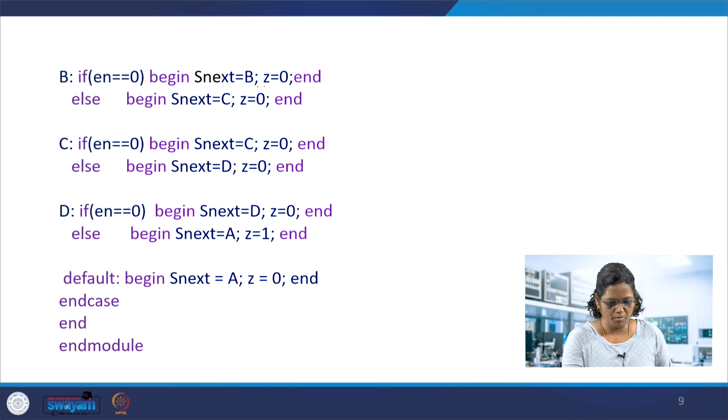So, here the combination of this next state and the output logic can be seen, which uses the blocking statement, preferable for the combinational logics. State memory is created separately.